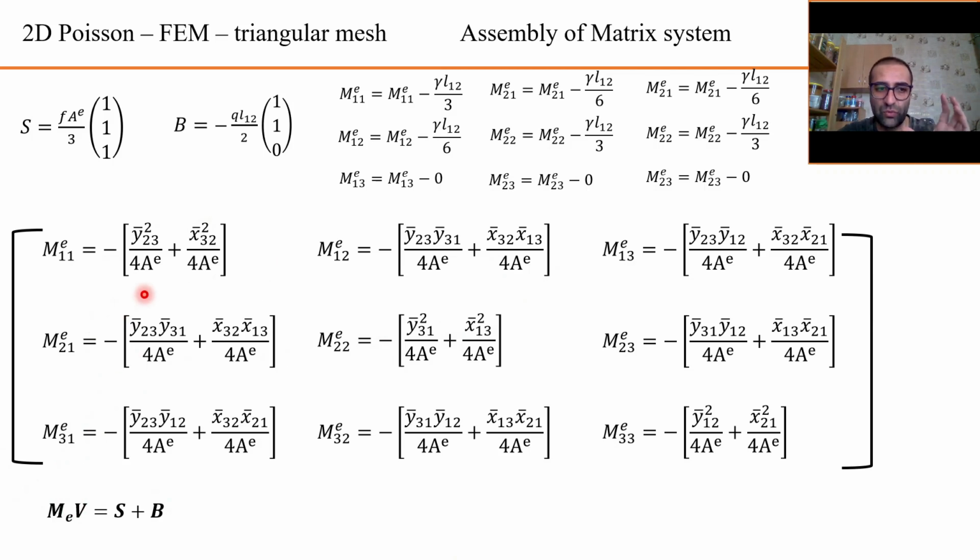Let's say this matrix for an individual element with M, and we know that if we indeed assemble the total matrix, the whole matrix, that is based on the number of elements and the connectivity, we finally have some K matrix times the V, and this V are the unknown coefficients at all nodes, and we have some right hand side matrix. Therefore easily we can calculate this V vector, just by calculating the inverse of this general matrix times the right hand side.